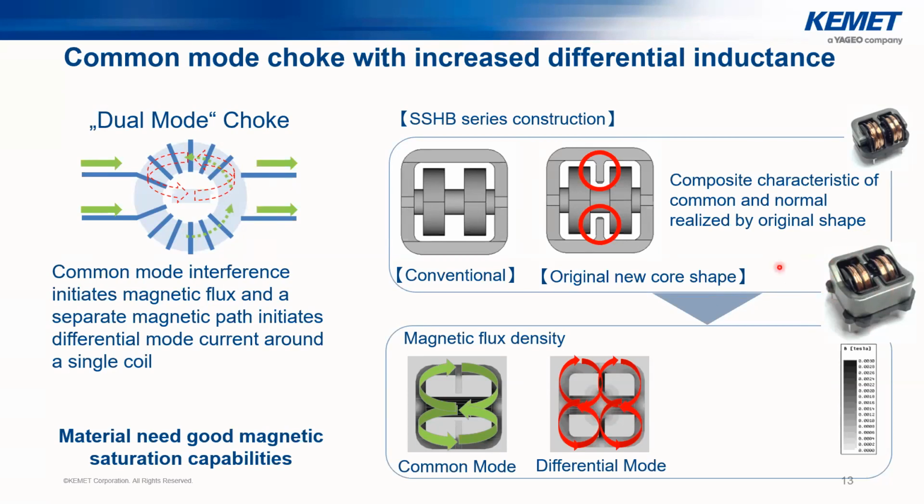So if you really need a big differential mode impedance for a signal, then either you use a smaller size differential mode choke plus this dual mode choke, or maybe you can increase your DC link capacitance, which is also on the same line, or maybe the capacitance of some other AC filter capacitor, or maybe even your X capacitor, which is also existing on the same line. So with certain strategies, there are many good ways of making use of such dual mode chokes.